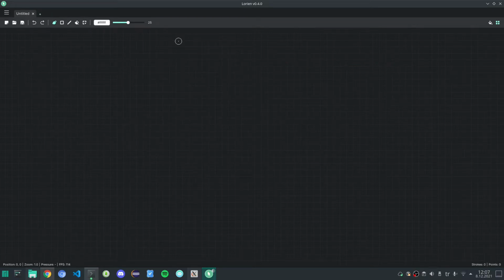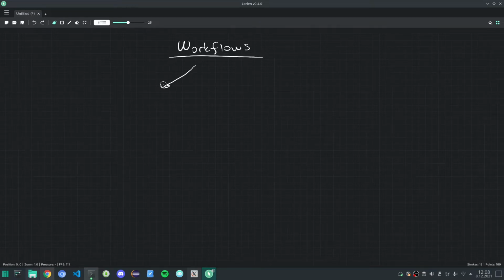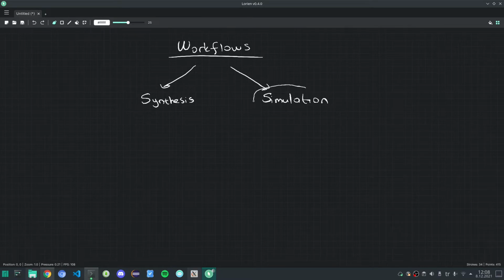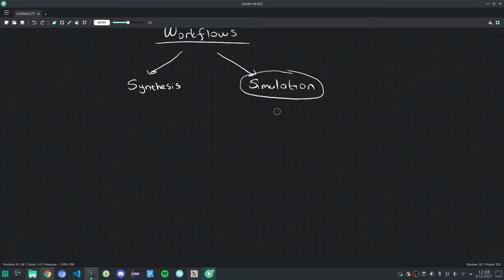Each HDL has its characteristic workflow. In VHDL, the workflow is started with the determination of the specifications. In other words, we need requirements to start any project, right? After the specifications are gathered and a design is prototyped, we start to generate the VHDL code. Following the code generation, the workflow is split into two, one for the synthesis and one for the simulation. In this lab, we will focus on the simulation part rather than the synthesis part, since we need real hardware for this part.